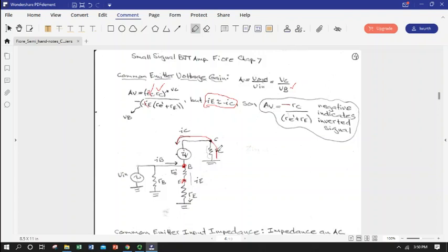Well, because the current's flowing this way. So if we start at 0 volts at ground, we actually drop voltage due to the direction of conventional current flow through our R sub C resistor. So V sub C is less than ground, whereas the base voltage, we're swimming upstream through that current, and it's a positive value versus ground. And in this case, positive is the magnitude, the amplitude of the voltage signal, but we can think of it the same way. It's the fact that we're flowing conventional current through the collector resistor, lowering the potential of the collector versus ground, which is the same reference point that we're using to define V sub B.